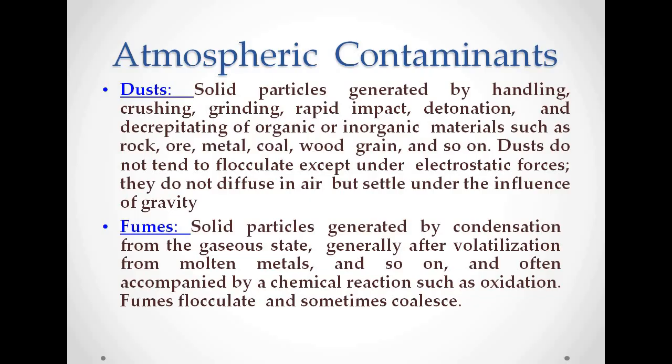First, if we consider dust, these are solid particles generated by handling, crushing, grinding, rapid impact, detonation and decrepitation of organic or inorganic materials such as rock, ore, metal, coal, wood, grain and so on. Dust does not tend to flocculate except under electrostatic forces. It does not diffuse in air but settles under the influence of gravity.